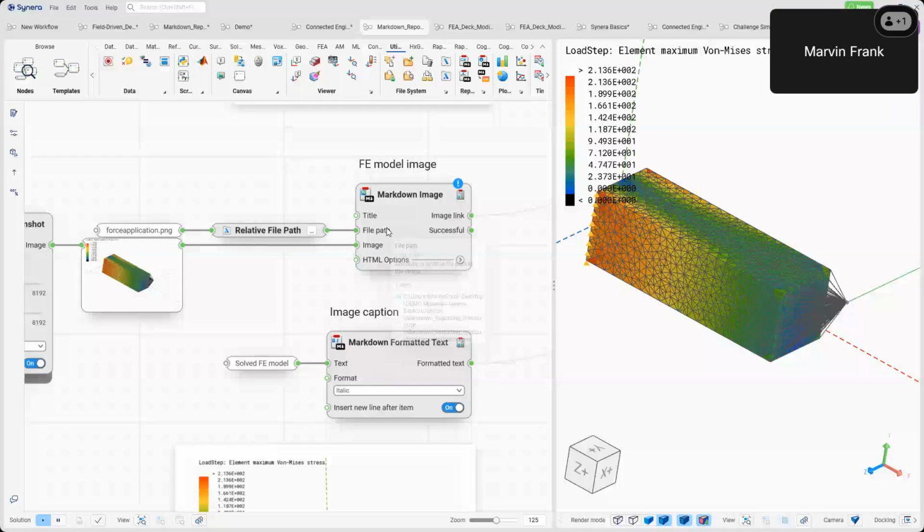For example, you can make a thickness optimization, a topography optimization, having beads by changing the design variable, the settings of the optimizer. And here, the interesting point is that in the workflow, you don't change it directly. So it's still an FEA setup, a shell thickness optimization, feed it into the OptiStruct optimizer.